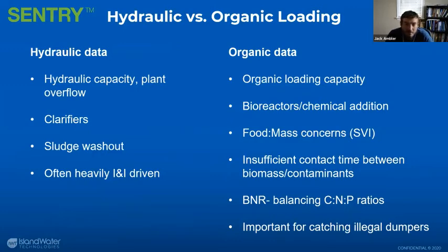The clarifiers have a lot of their stuff based on flow, just flow rate, not necessarily concentration. Are you going to push too much of your return activated sludge or waste activated sludge out of the system by doing sludge washout? And it's often driven by the I&I events. So you're primarily worried around big rain, melt, or whatever types of I&I conditions.